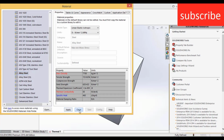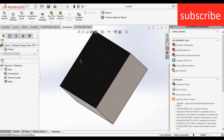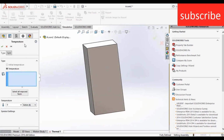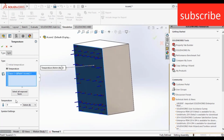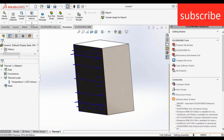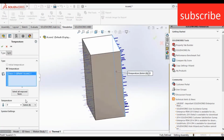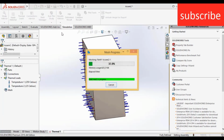So make sure you always choose a material whose value is given in Solidworks. So apply and close. After that, what I am going to do is apply the temperature load. So click on temperature, select a face and set the units, for example 250 degrees Celsius. You can enter the value as per your requirement, click on thermal loads, click on temperature and select this face and select the temperature as per your requirement. Click OK.